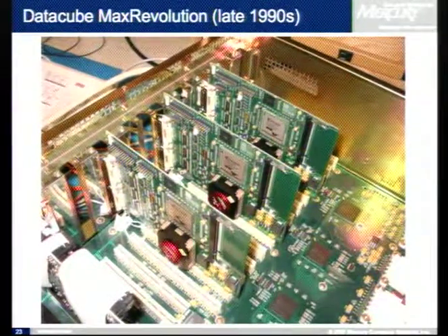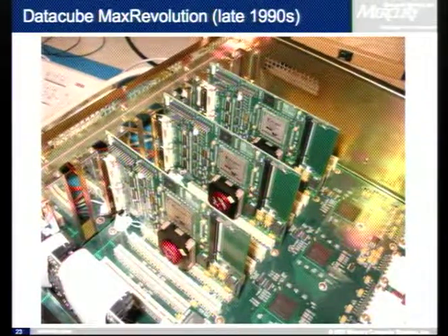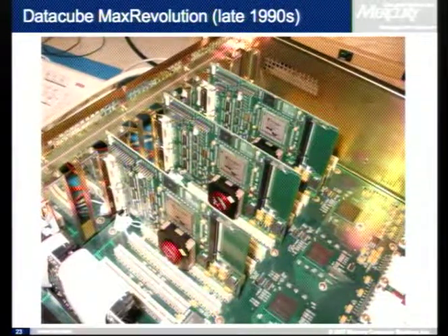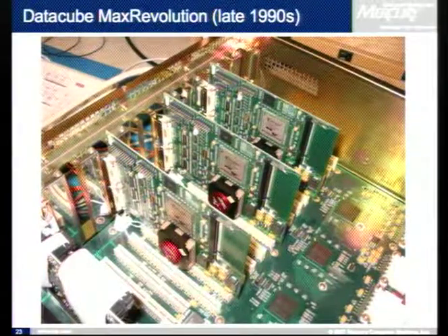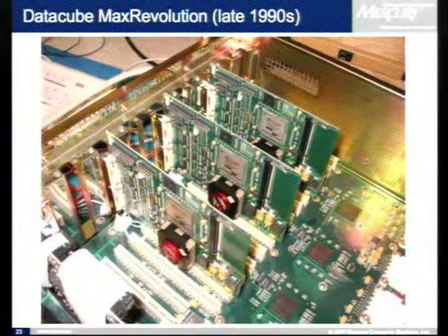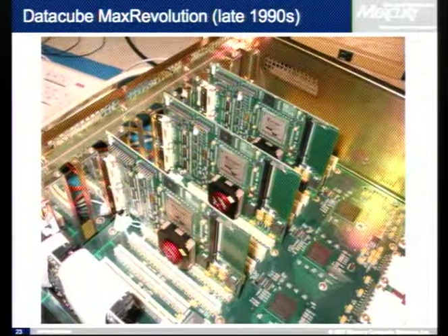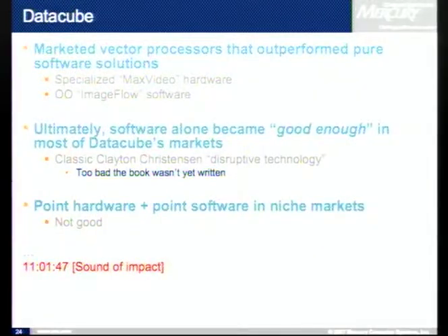Anyhow, by the end of the 90s, FPGAs were driving all of these integer image processors that Datacube was making. Here's an example of one of them. They're being used in digital angiography, web inspection, machine vision. That's probably a Xilinx 2000 or so device, and a QuickLogic DMA engine serving as both a PAL-like device and the DMA agent between PCI and the processor. So all of the dedicated hardware, the TRW multipliers, the fancy YTech floating point chips, all gone, basically driven out by FPGAs. But there was a problem.